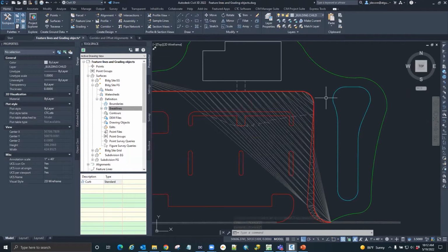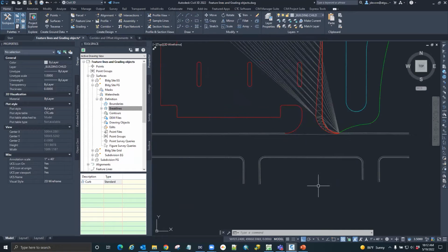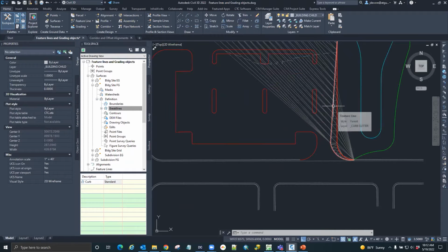But from what I've found, stepped offsets and working with feature lines is a quick way to get something through. Or if I'm already at my final design, maybe these are final tweaks that I'm adding, maybe to a valley gutter or to a curb inlet or other things like that. So Felix, what's your opinion on feature lines and stepped offsets there?